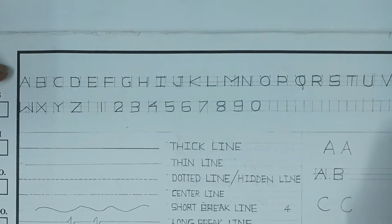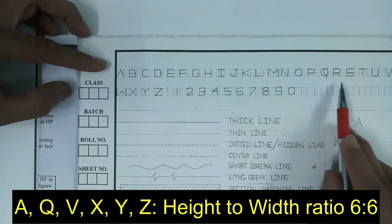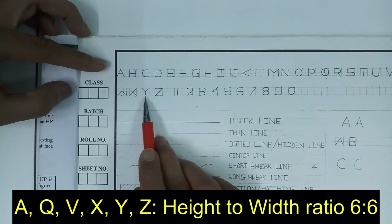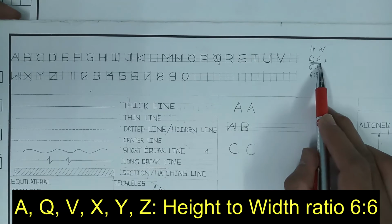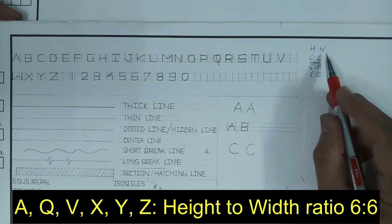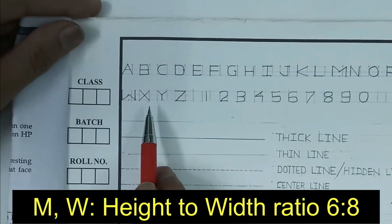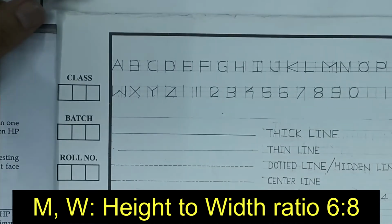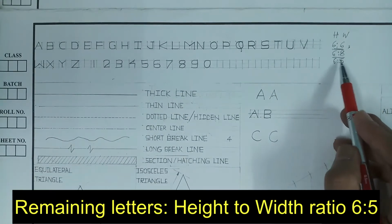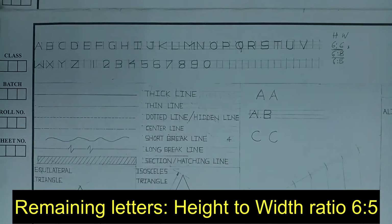As a general practice, letters are specified by height to width ratio. Generally letters A, O, Q, V, X, Y, Z are all drawn with a 6:6 height to width ratio, where 6 is height and the other 6 is width. Letters M and W require more width, so they are drawn with a height of 6 and width of 8 millimeter. All remaining letters, excluding the ones I have just mentioned, are drawn with a height to width ratio of 6:5.